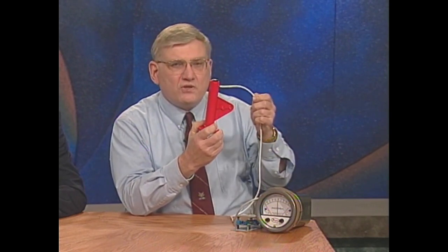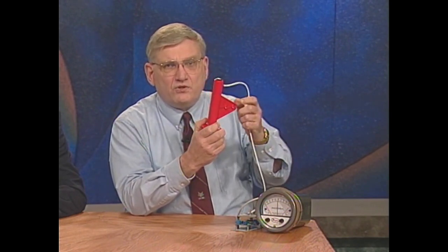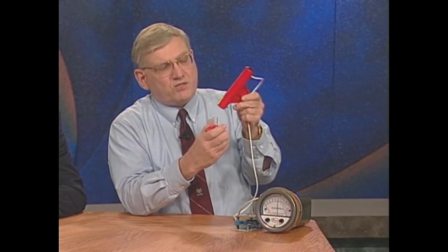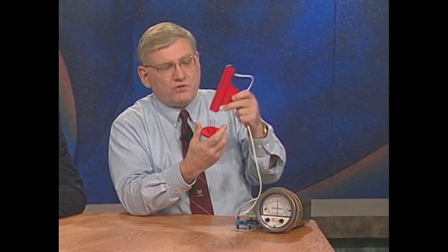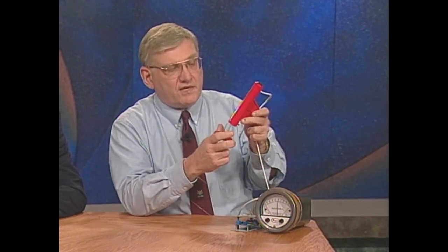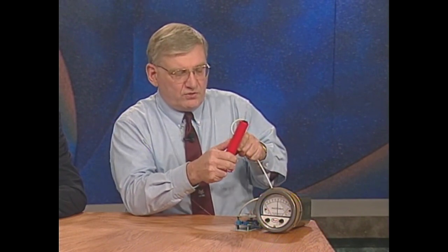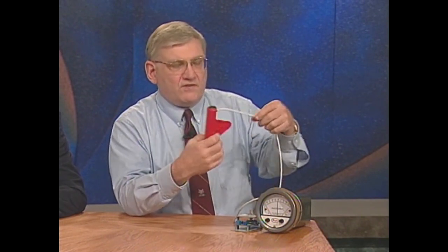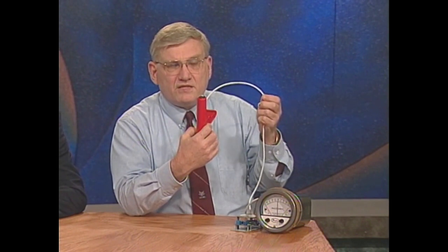A critical design issue is making sure that water does not get into the tube and block the tube. This expansion tank inside the unit makes sure that the water has to go up vertically, and since it doesn't, it keeps it out of this tube. If this tube gets blocked, the system will become rather unresponsive because air cannot get through it.